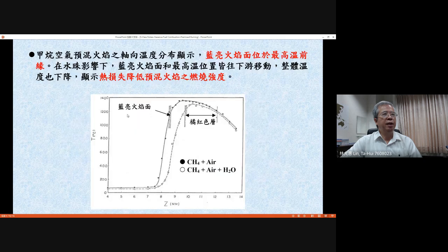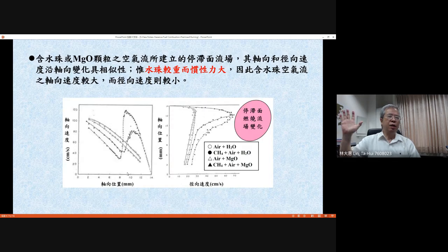You understand there is the high temperature in this region, right? Temperature high at this point and a temperature low on the upstream side, then you will have a so-called thermal expansion to the upstream side, and this expansion will reduce the actual momentum of your gaseous flow, which means that the actual velocity will drop very fast, and they will move to the minima point around 8 millimeter.